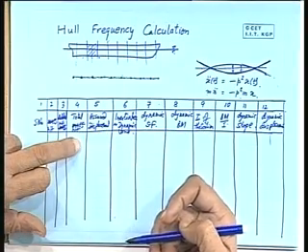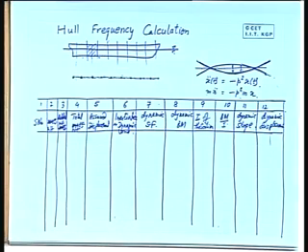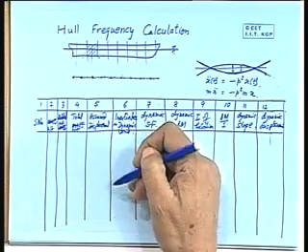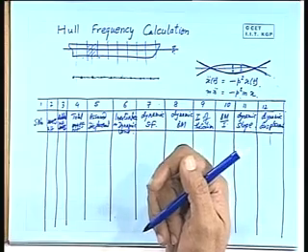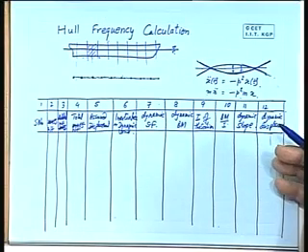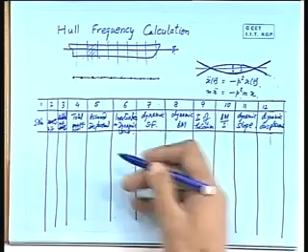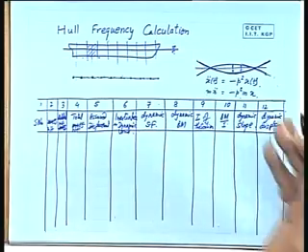So what is done here is that the assumed displacement is assumed as a fraction of the maximum displacement. That means wherever you are taking the maximum displacement, that is unity, and the remaining are all fractions of that. So here also, whatever the dynamic displacement you get, you try to normalize it by dividing all the values by the maximum value here. And then you are going to get the normalized value, and then you try to compare it.